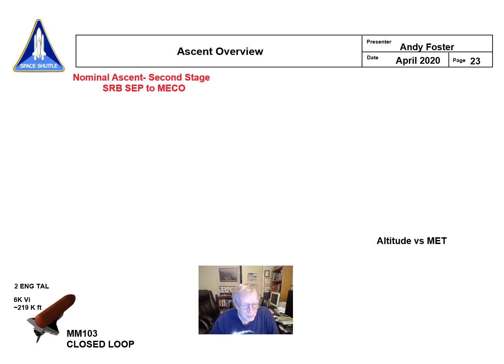Right after SRB SEP, you're really close to about 6,000 feet per second inertial velocity. You typically pick up what we call 2-engine TOW capability right after that, which meant that if I had an engine out before this, I would have had no option but to do an RTLS, or return to launch site abort. Again, that's covered in the RTLS briefing.